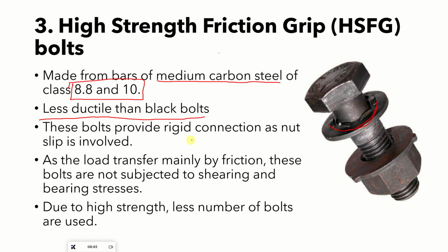These bolts provide a rigid connection as there is no slip, as load transfer is mainly by friction. These bolts are not subjected to shearing and bearing stresses. So these are very strong, so we may need a smaller number of bolts for the connection.